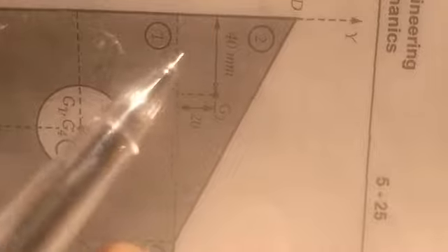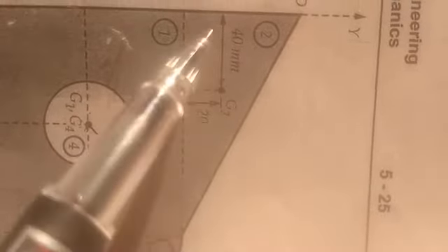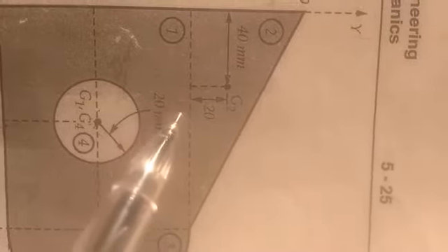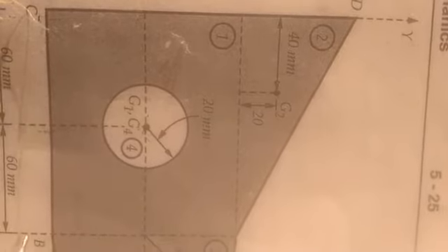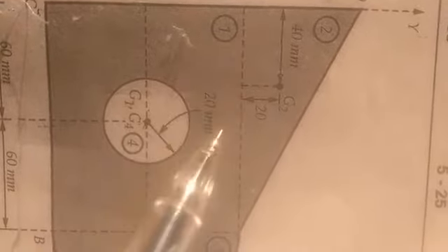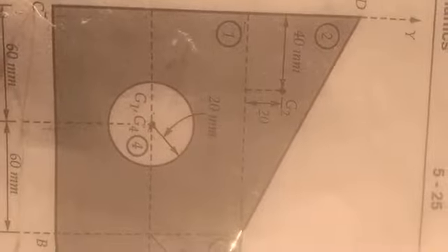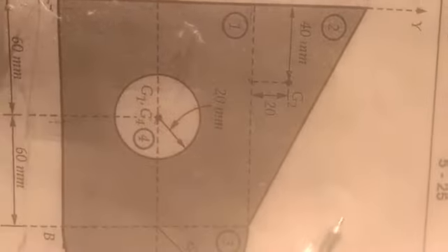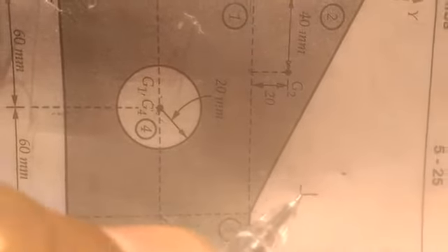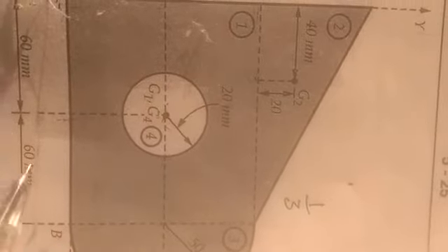Come to the second section. In this, the CG arises at 2/3 if you come from here, and 1/3 from the other side. The base of the right angle triangle is 60 plus 60, which is 120 meter. So the CG arises at 1/3 from this side. If you come from this side it will be 2/3. So take 1/3 of the base distance, 120. If you cancel, 3 fours are 12, so 40. At a distance of 40 meter the CG will arise. That is the x distance.